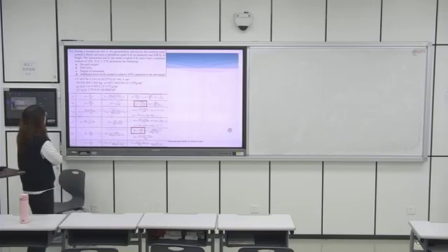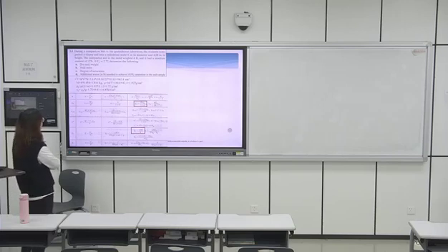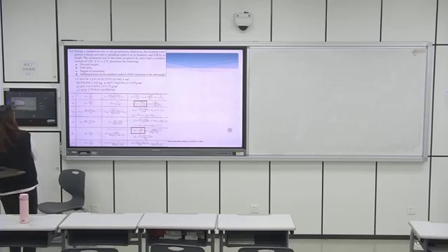It says that during a compaction test in the geotechnical laboratory, the students compacted a clay soil into a cylindrical mold, 4 inch in diameter and 4.58 inch in height. The compacted soil in the mold weighed 4 lb and it had a moisture content of 12%. If Gs equals 2.72, determine the following. First, dry unit weight, and then void ratio, and then degree of saturation, and finally additional water needed to achieve 100% saturation in the soil sample.